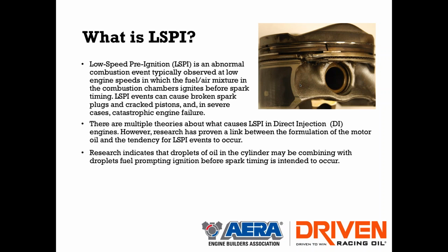And what it looks like from the advanced engine testing and a lot of fundamental research is that the droplets of oil in the cylinder wall and in the ring package seem to be combining with droplets of fuel. And that combination of the oil and the fuel, this is where things can go bad.